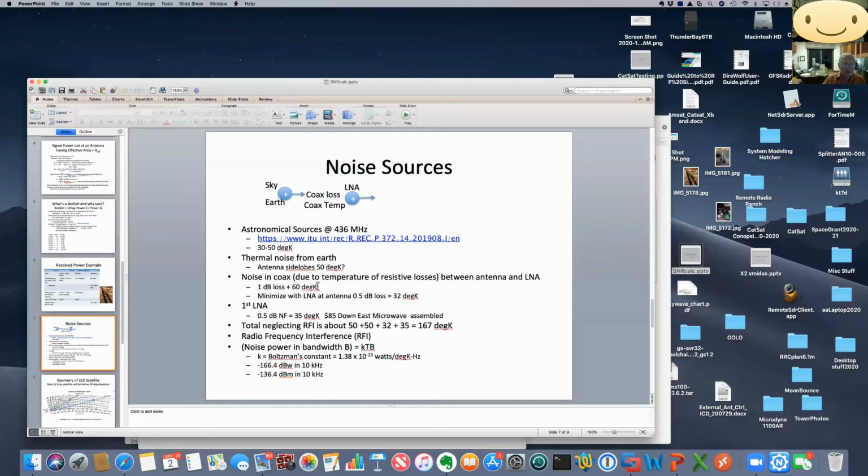If the cable were really attenuated, like maybe 10 dB attenuation, the noise temperature would be what? It would be the same as the temperature of the cable, which would be 290 degrees Kelvin. So should that be an equal sign, not a plus sign there? No, I'm just saying the 60 is a 1 dB loss, and what I'm trying to say is add 60 degrees Kelvin to the sum of these two numbers. Right, but 60 degrees is equivalent to 1 dB loss. So that should be an equal sign.